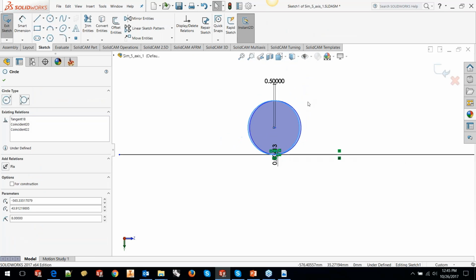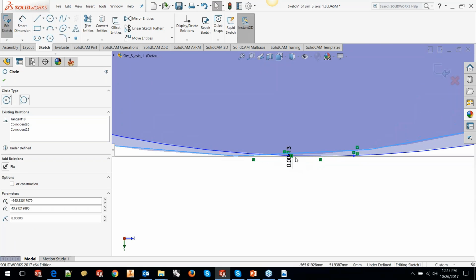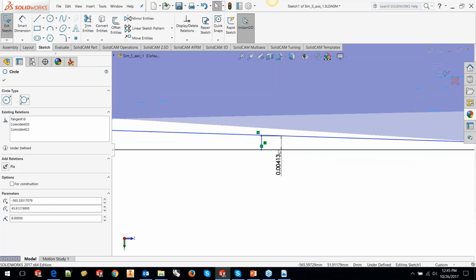So this is diameter 16. That's the ballnose tool. When a diameter 16 rolls over a flat line, I've just created a line to show the contact. To achieve a scallop of approximately 4 to 5 microns, okay? 4 to 5 microns generally is considered to be a pretty good finish on such parts.